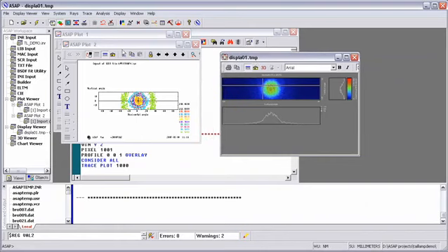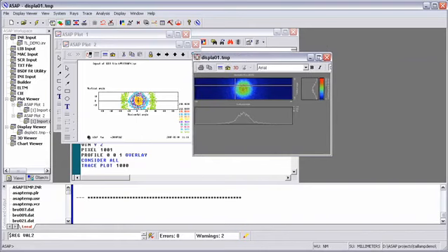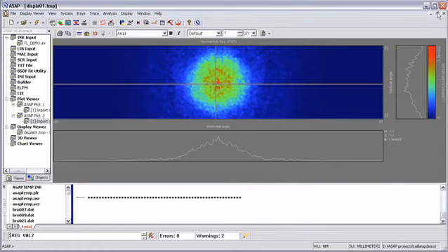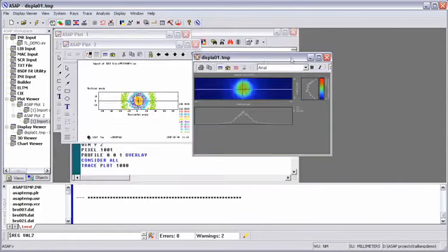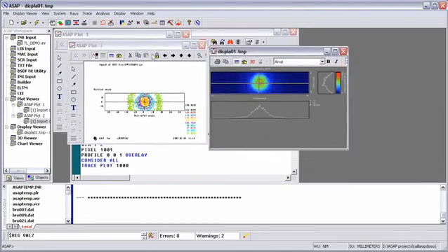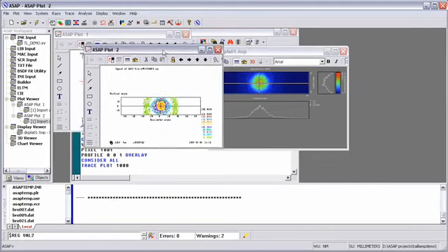You'll notice that the resolution for this particular demo is a little bit low. We've traced a smaller number of rays than we would normally trace for an entire simulation. For the final output, we would run upwards of 3 million rays. In this case, we've run only a couple hundred thousand. The 3 million ray trace might take 45 minutes to an hour to complete.